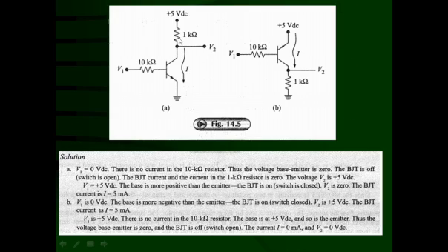This you can see in this circuitry. This is NPN transistor. So the collector is given a positive terminal 5 volt with respect to emitter, that is the ground. If the input voltage V1 is going to be 0, that means the base emitter junction is reverse biased and there is no base current, so there is no collector current, ICRL is going to be 0, so that same voltage is going to appear over here. So 5 volt will appear here and V2 is equal to 5 volt. And if V1 is equal to 5 volt, that means the base emitter junction is going to be forward biased.